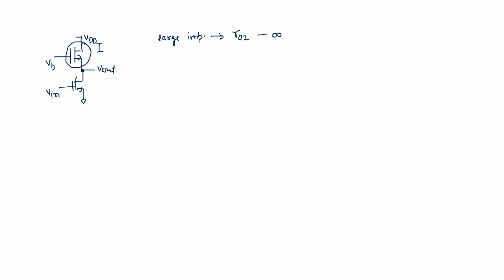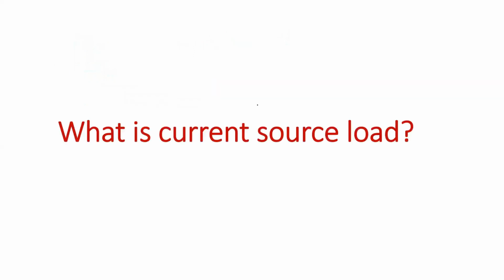to infinite. If we are using a MOSFET, this is M2, which is also in saturation. Or if it is an ideal current source, then it will offer infinite impedance. So overall, in this case, the gain is minus gm of the primary transistor times the parallel combination of ro1 and ro2, if I'm using M2 in saturation as a current source.